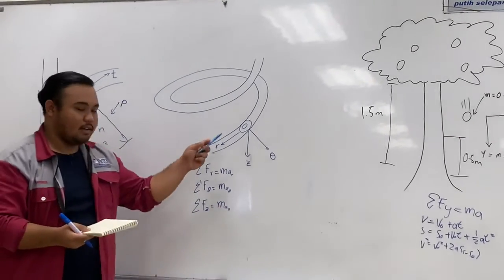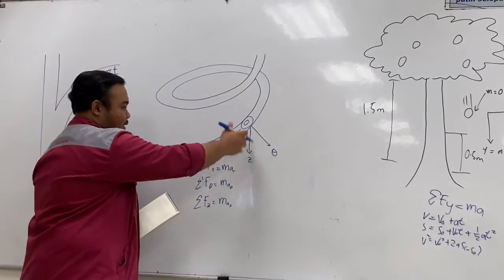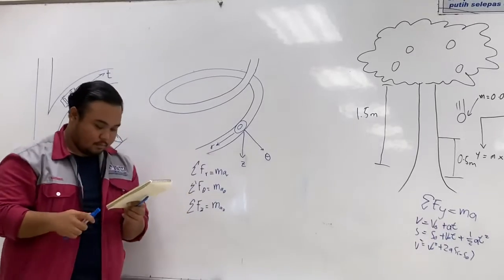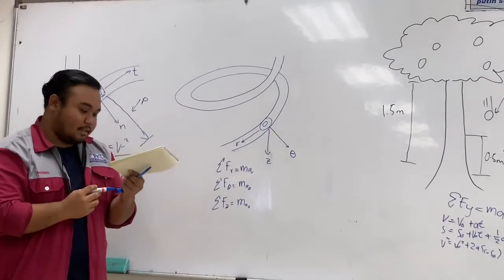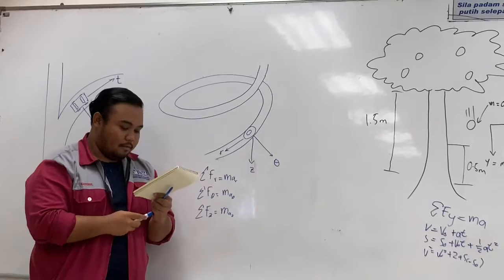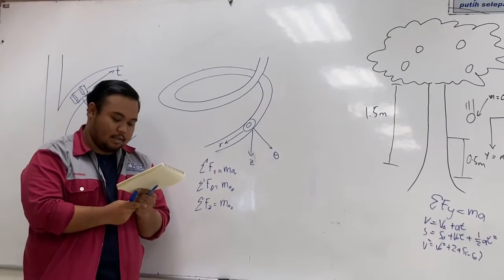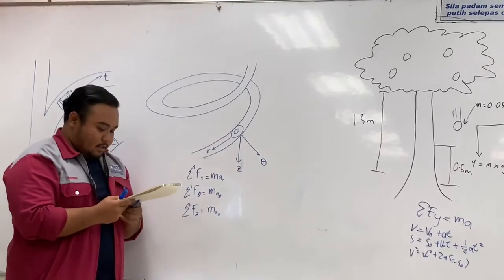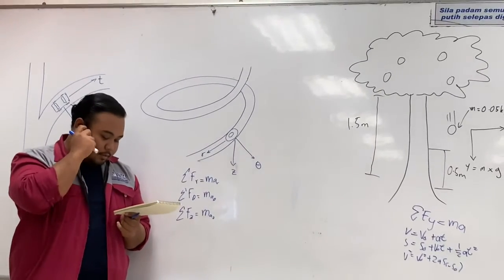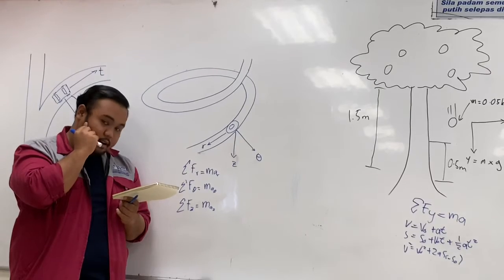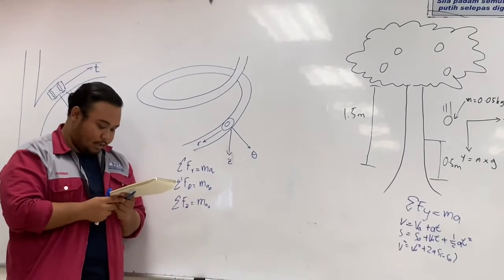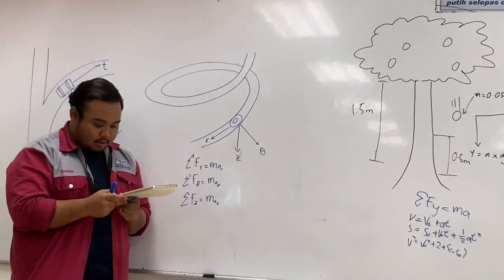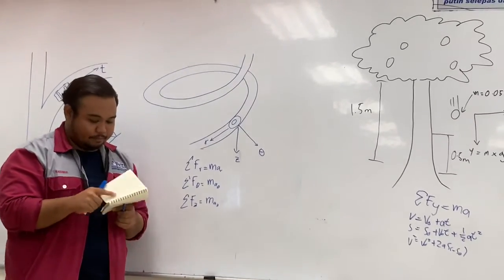As you can see from the diagram, these are the axes involved when a particle moves along a cylindrical path. Cylindrical coordinates require the determination of the resultant force, which causes a particle to move with a known acceleration. Cylindrical coordinates are a suitable choice for the analysis of a problem for which data regarding the angular motion of the radial line is given. Once these coordinates have been established, the equation of motion can be applied.